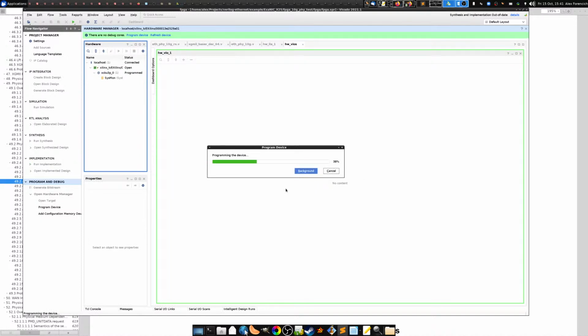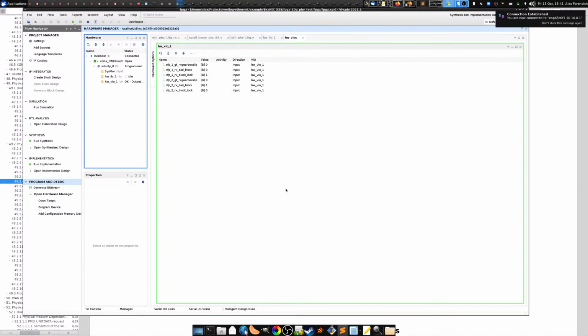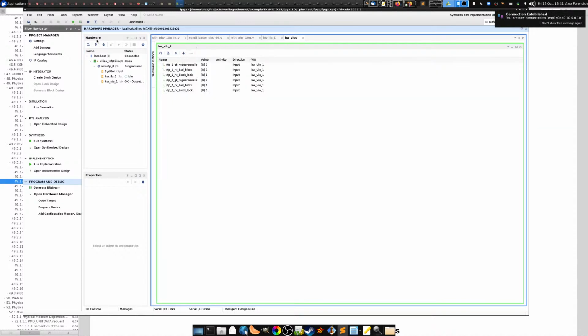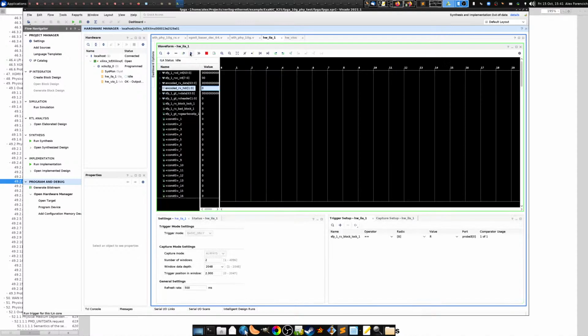This is one annoyance with the way the GTY Transceiver wizard is set up. They don't have a checkbox or something to isolate the resets across the different channels. I don't know why they don't do it that way, because that would simplify a few things quite a bit. All right, let's see if my ILA is working now. Nope. All right. I'm gonna try one other thing. Where did I put that thing?